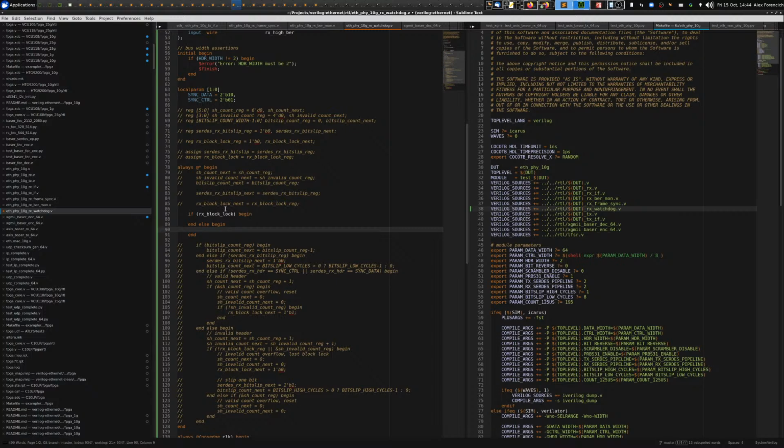So 100 microseconds or so, if we see problems, then we set a flag, and then if we see problems in several 125 microsecond time periods, then we reset the transceiver. I think that makes a fair amount of sense.